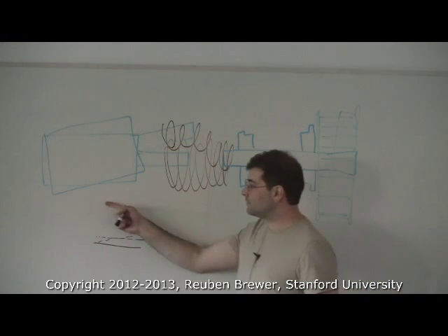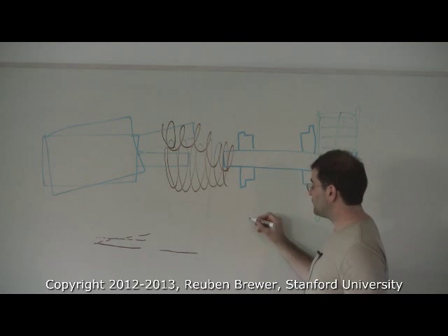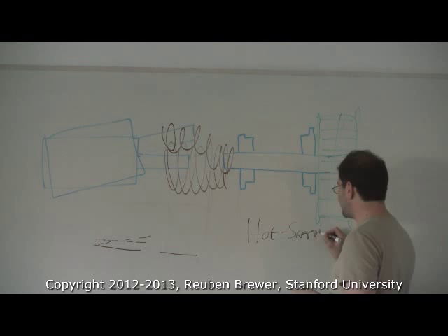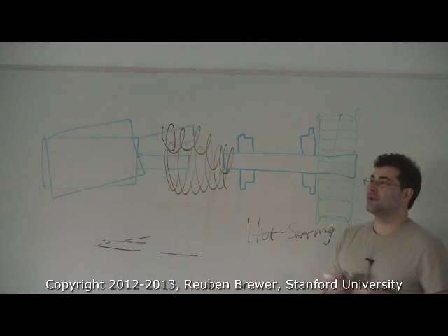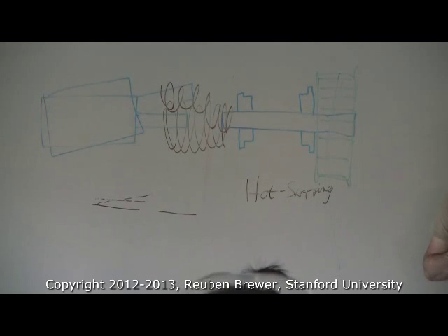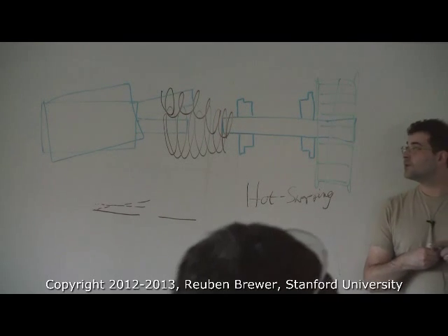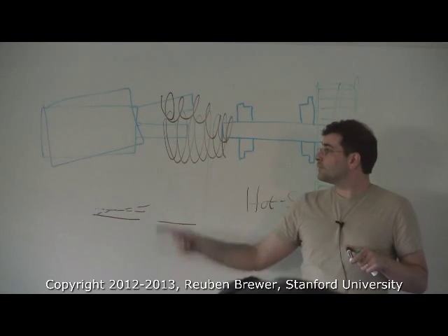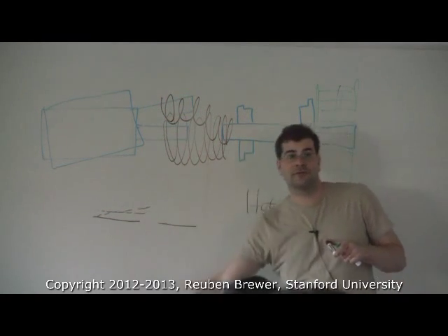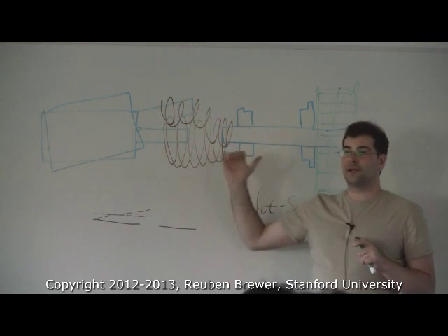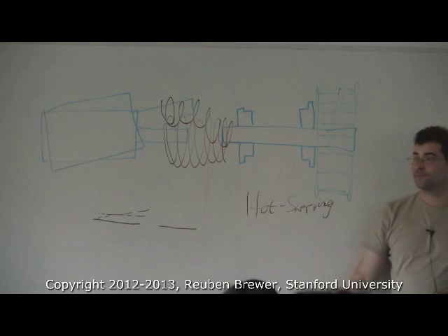So in terms of why we use the flexible shaft coupler, I like to call it hot swapping. Say what might happen next month when I turn my robot on is I find out an RE30 isn't big enough. I need more torque. Well, because I've done it this way, literally all I do is undo 4 bolts, 1 screw for the clamp, take my motor off, I put on an RE40 or 50, 4 bolts, 1 clamp, and I'm done. I don't have to take apart crap.